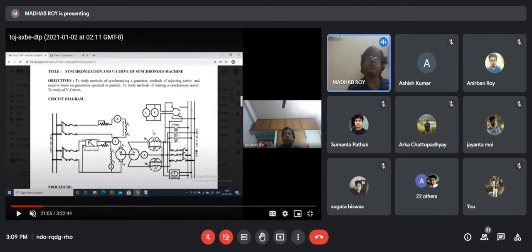You have to remember the three-phase wattmeter method. When the power factor is one, it will be only then that both wattmeters will read the same. By the reading of both wattmeters, the sum in kilowatts will be displayed, and by knowing the rating of the generator, what actual kilowatt it should deliver for rated condition, by the summation of these two wattmeters we can have the starting point of the experiment.